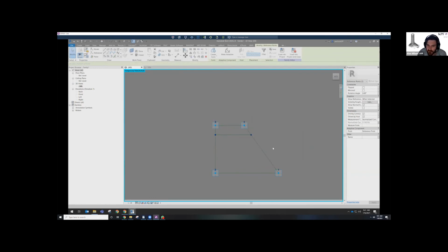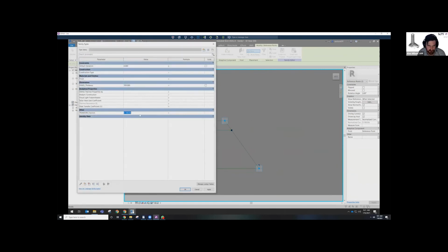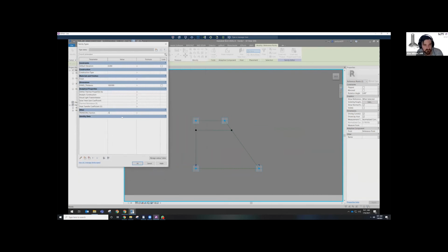If I just create a parameter, we can start to play with this number here, and you'll see it kind of in action. So let me just pull this over a little bit. If I change it to 0.5, which is going to be the middle, and I hit apply, this is halfway between those curves. It kind of actually does look like it's shifted a little towards the top. This segment's actually bigger, but that's just a bit of an optical illusion because of the points. That's actually the center, but you can start to just change the number.